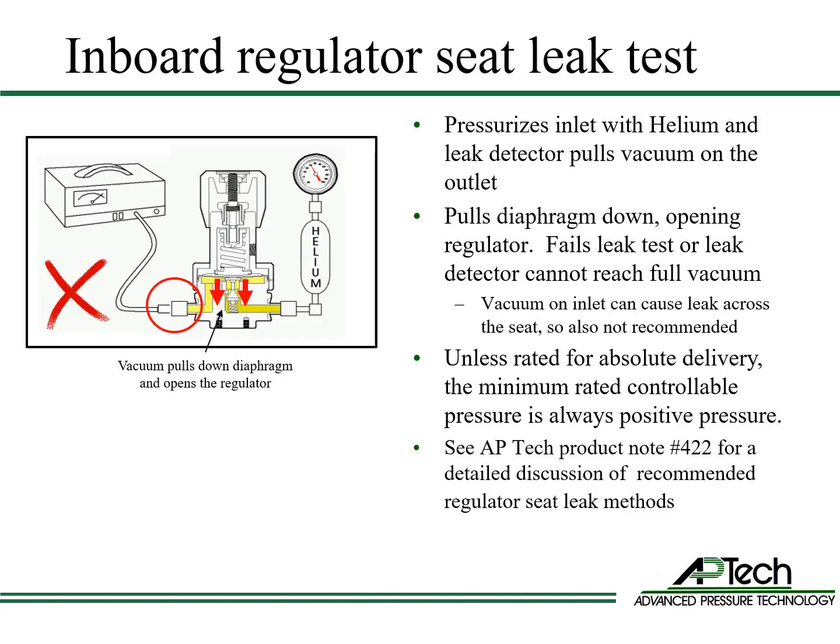The helium inboard seat leak test is not recommended for regulators because unless you're using a subatmospheric regulator, pulling vacuum on the outlet of the regulator will often open the regulator, breaking the seat seal and exposing the low pressure side to pressurized helium. Vacuum on the inlet is also not recommended because it can cause a leak across the seat. A regulator does have a vacuum inlet pressure rating, but it's intended for purging, inboard testing, and system flushdown